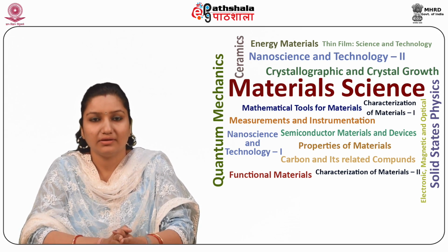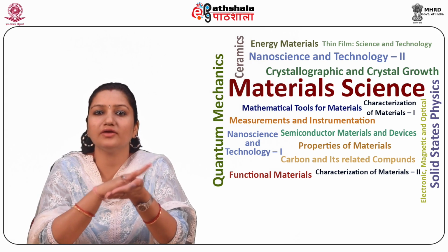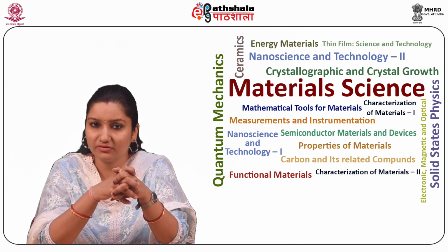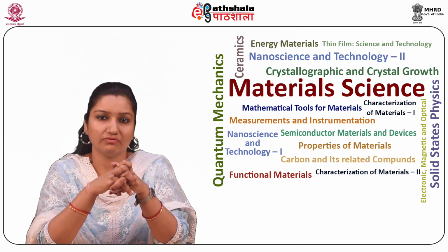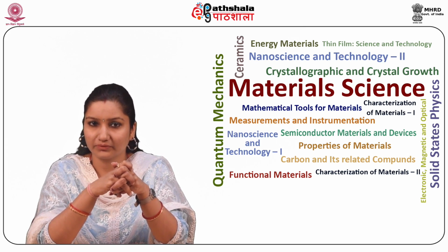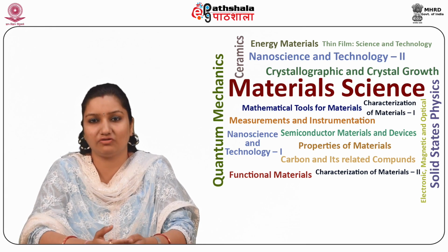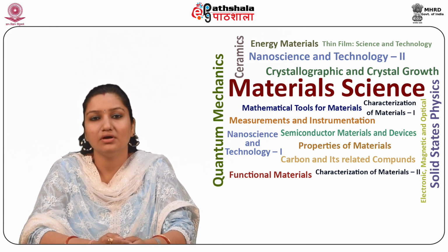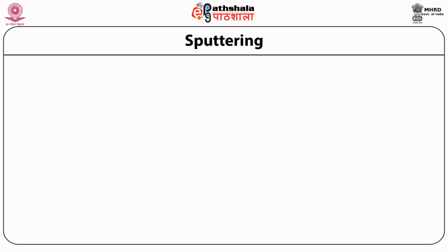This technique is an efficient tool to deposit multi-layer films for mirrors or magnetic films for spintronics applications, that is, devices using the spin of electron and hole along with the charge on them. Sputtering.